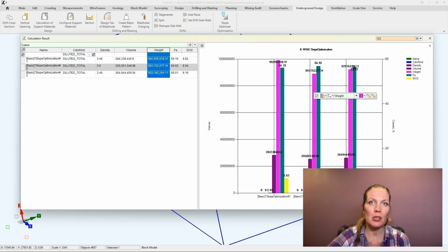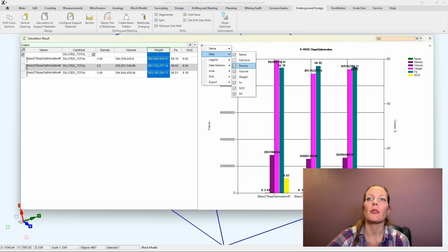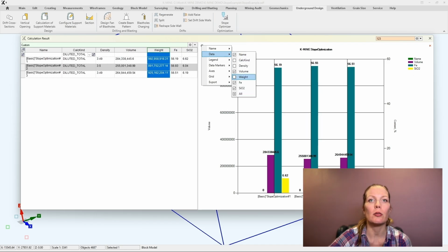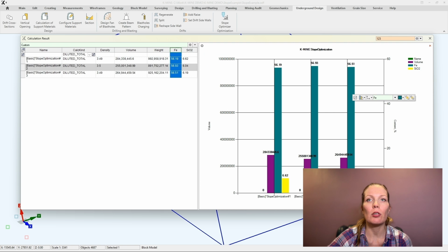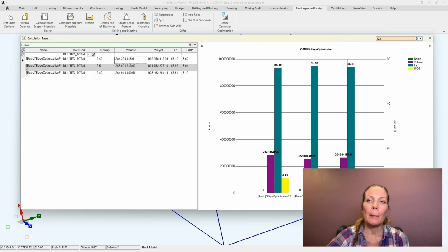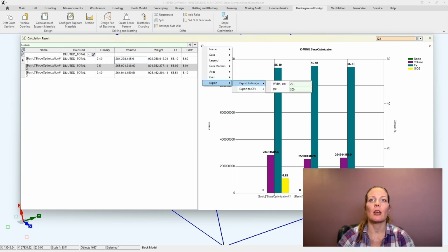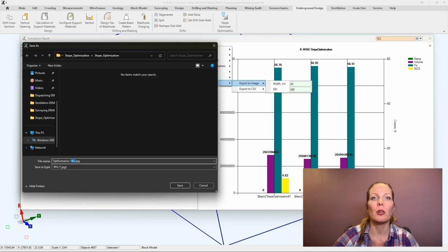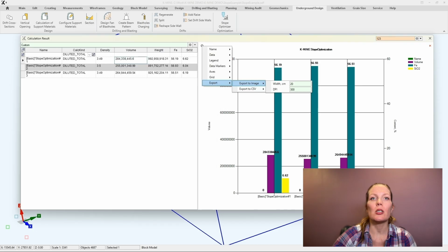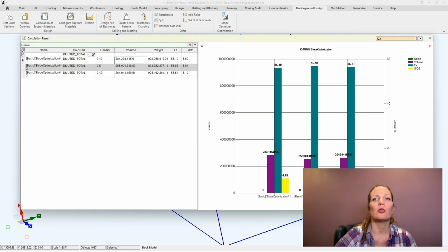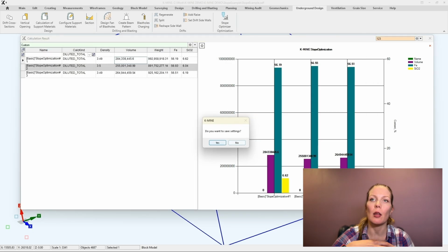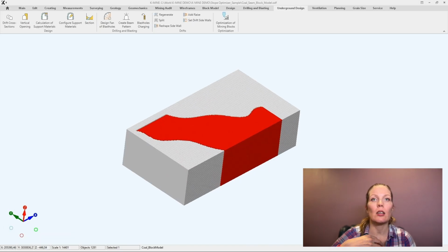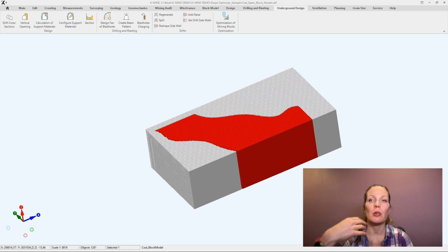Refining the stope comes next. K-mine can adjust sidewalls, modify the stope's incidence relative to the ore body, and tighten adherence to the valuable zone. The method context matters. So for narrow gold veins, adjustments keep mining width minimal and avoid pulling barren rock. For sublevel stoping in massive bodies, a refinement smooths edges and removes block model artifacts, leading to more stable drilling, blasting and backfilling. The output is a set of stopes already shaped for immediate use in design.